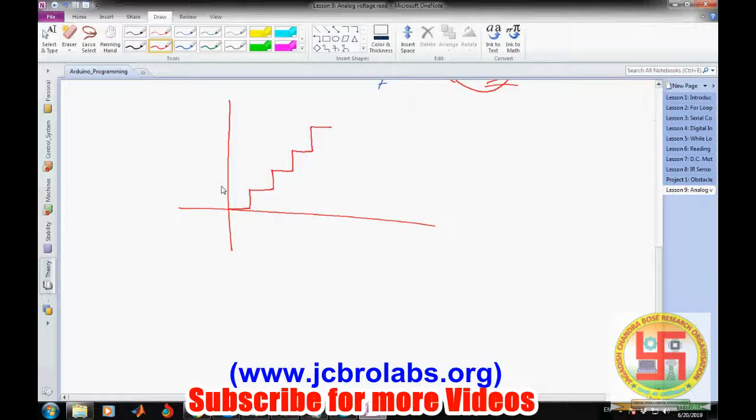So here we represent the number or the digital code. Let's say it is 000, 001. We are talking about a 3-bit ADC: 010, 011, 100 and so on. And on this axis we represent the input voltage. So this is the corresponding digital code.